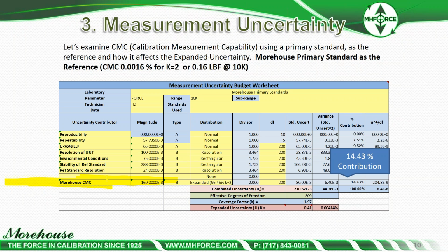So we're going to take the degrees of freedom, the types, and the standard uncertainties, and we're going to get a percentage contribution in here, and determine what our coverage factor really needs to be to ensure 95% confidence. Down here in this particular example, this number would be multiplied by 1.97.